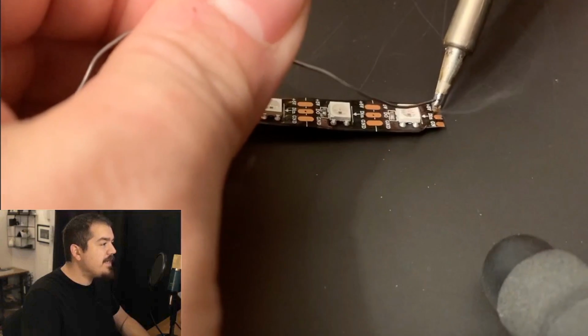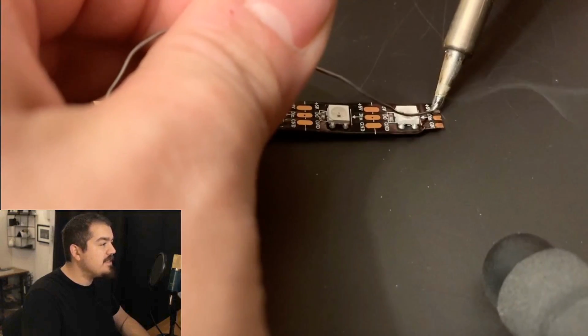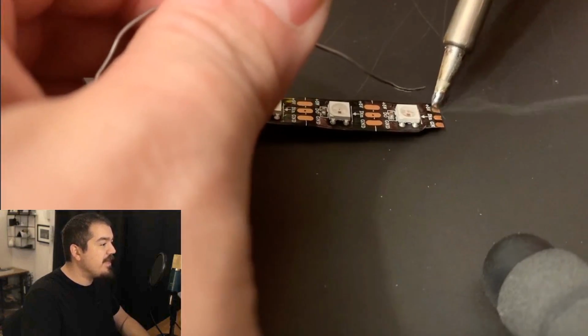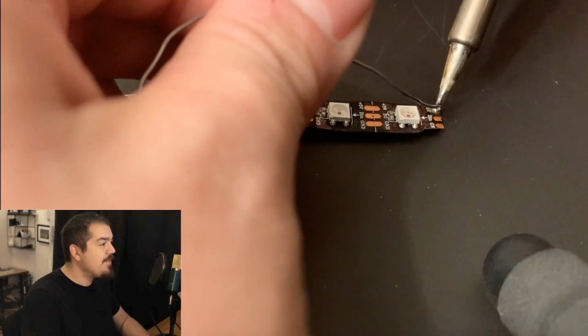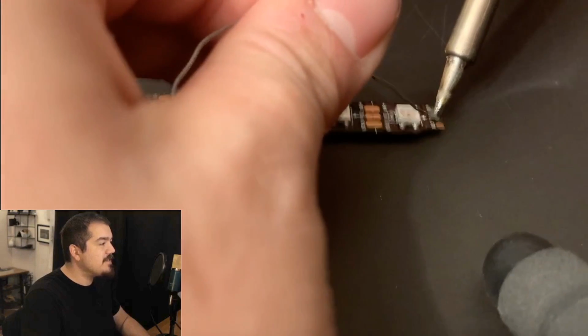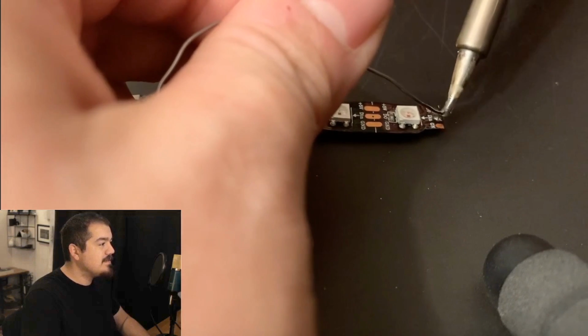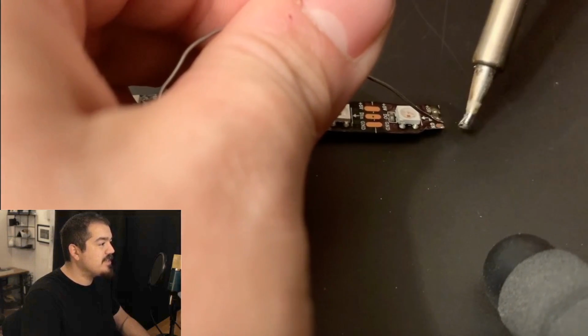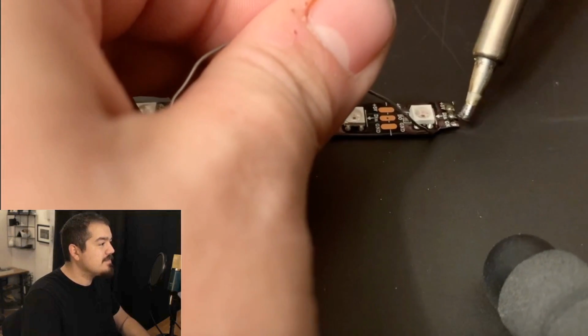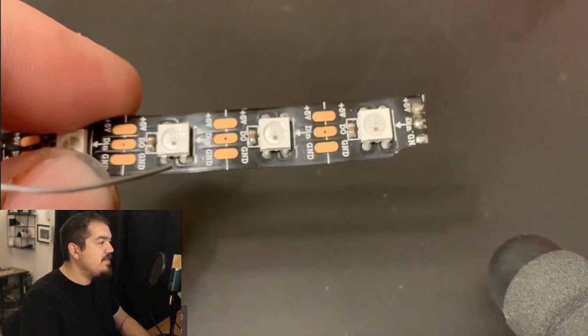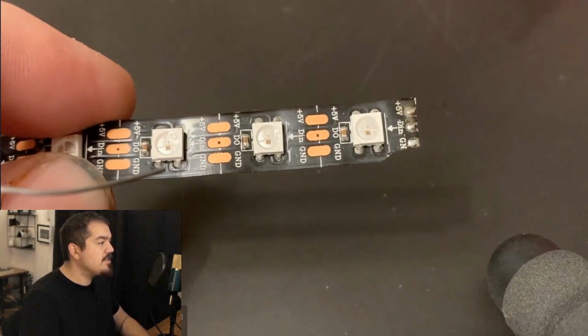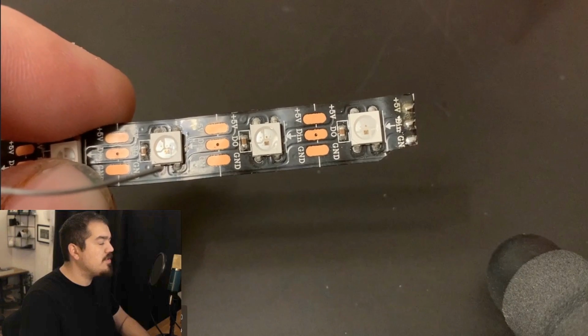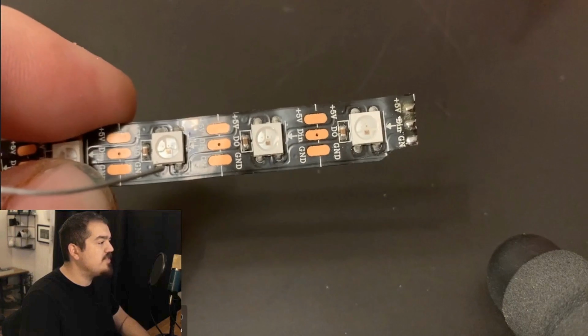I'm going to start off by getting just a little bit of tin on the pads here. This is a lot easier with the third hand and when you're not on camera, but I just want to get a couple little dots onto each of these pads. You can see that one's pretty big, so I'm moving it on to the next one. You might have a little bit of flux spread around, but when you're done, it should look like this, where you've got the pads well coated, but there's no solder moving in between them.